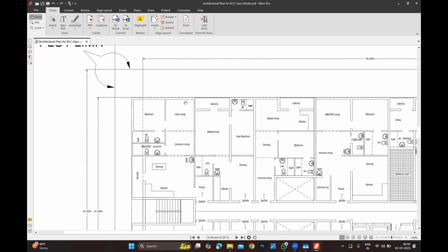But fortunately, when you are going to place the column, if an opening is there, don't try to accept it as it is. Try to place the column a little bit away from the vertical. Maybe there's no possibility, but I'm telling you, 90% of the time they have a solution. You got it? In a corridor, if there is a corridor, don't place your column exactly at the face of the corridor. Try to keep the columns a little before, half a meter only.